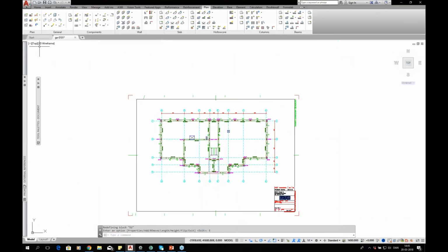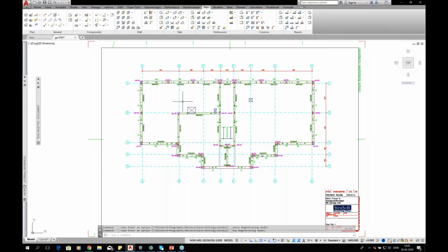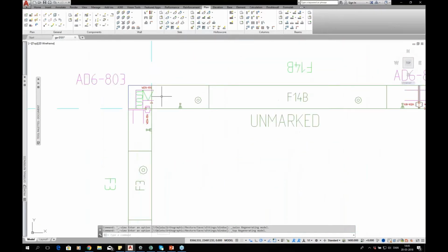So now we've worked for approximately 15 minutes, and we actually have a plan here. Sandwich panels, lifters, elements that are split up, calculated centers of gravity, and pretty much everything we need here. We want to do some more detailing. Of course, we want to do the corner connections here with wire loops.